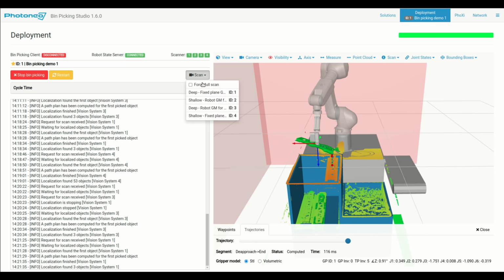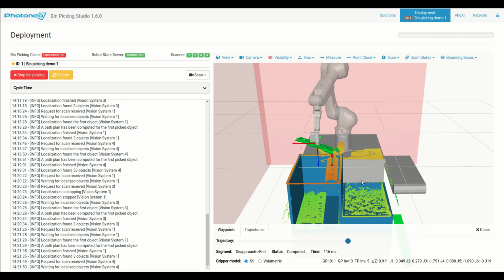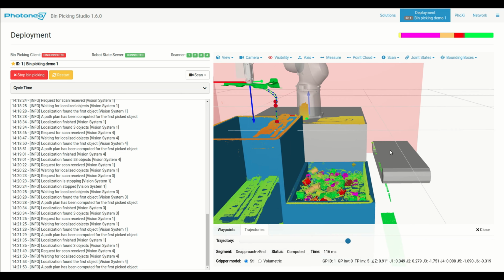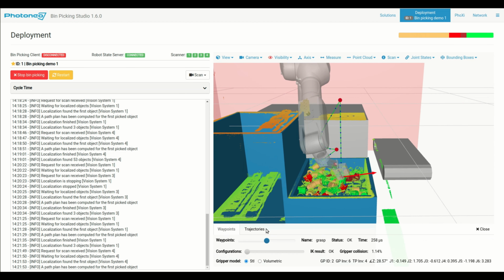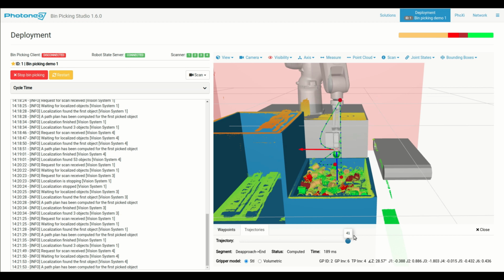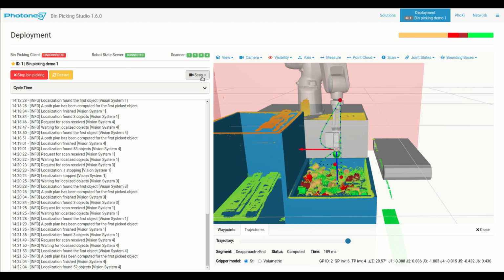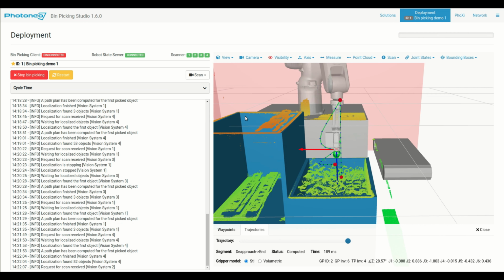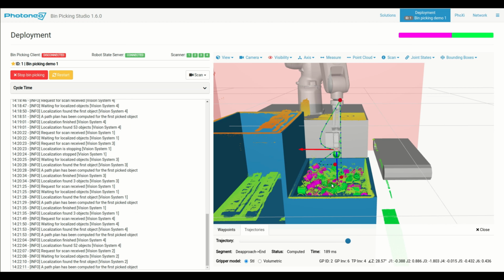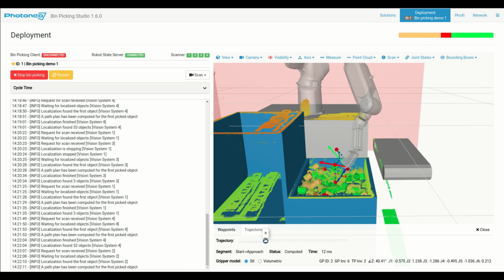The other object is small, placed in a shallow bin with its upper edge much lower than the upper edge of the deep bin. Using the same grasping method as for the first object, the D-approach waypoint would be too high, which is pointless. Here, the default grasping method, where the D-approach waypoint is defined at 10 cm above the gripping point, will suffice. This way, we optimize the grasping method for each vision system.